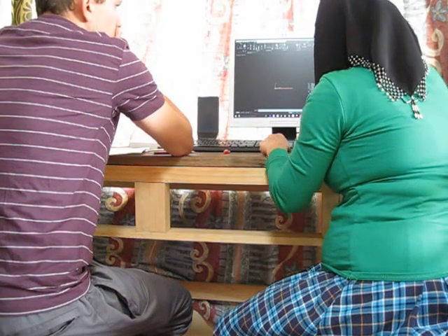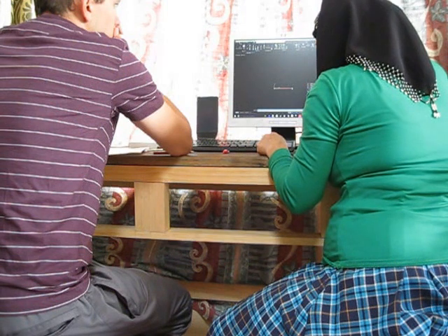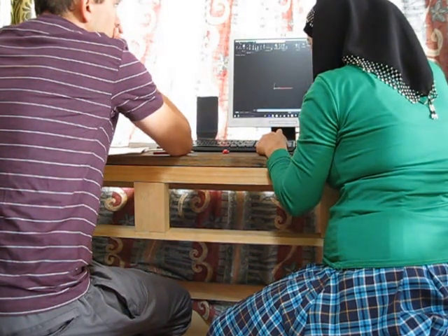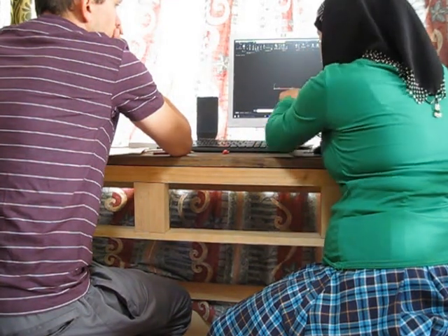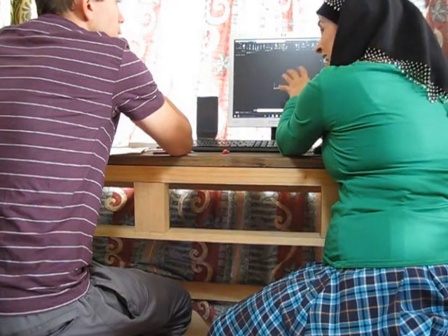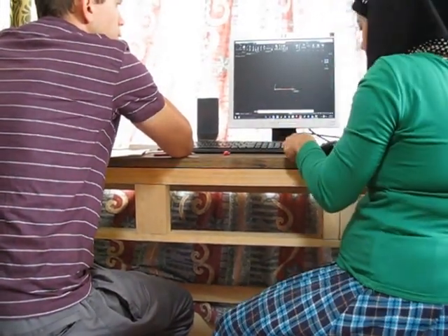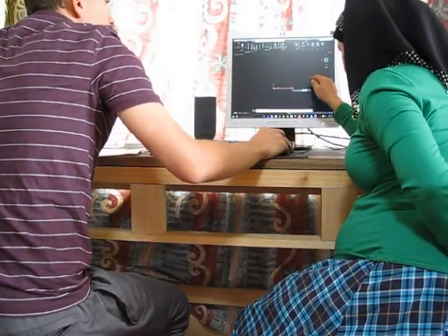So when we click on this, you can see the node. You can't see the endpoint. Why? Because you haven't clicked on the line. You have to click on the line. When you come here, did you see? There is a green square. That green square is the endpoint of this line. Click on this end of this line because we want to start another line.